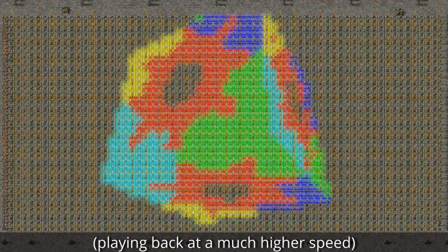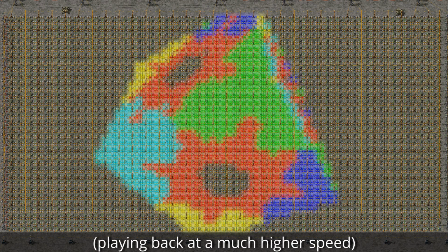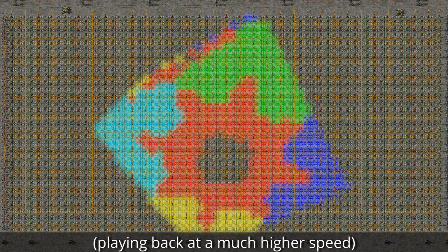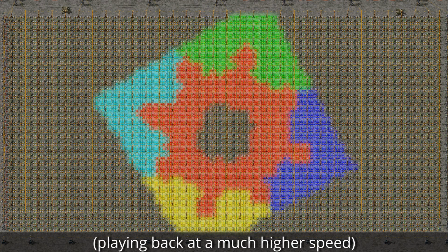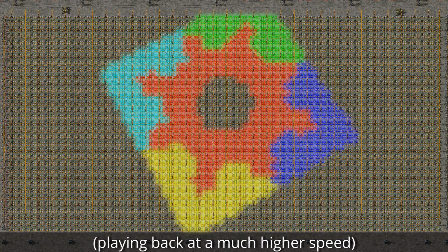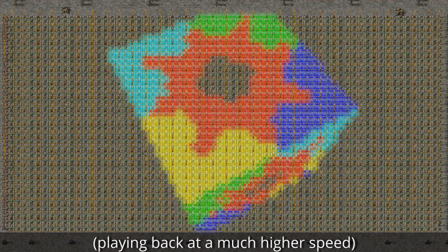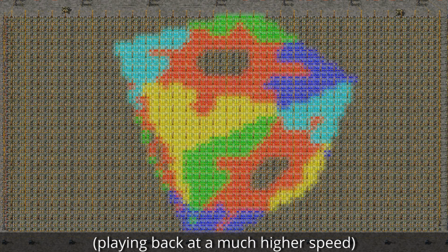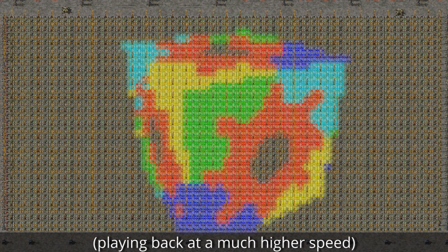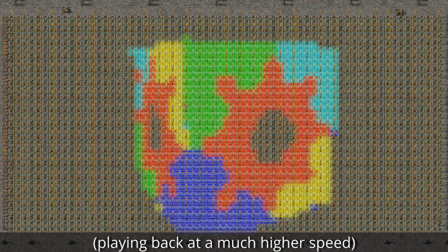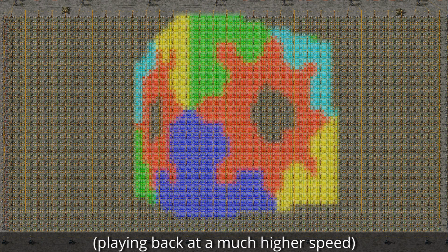It can render an arbitrary number of perspective projected texture mapped triangles to a 64 by 32 8-color screen at a rate of 1 triangle per tick, plus an overhead of about 2 ticks per completed frame. The textures are all 32 by 32, and in the current design up to 4 textures are supported.